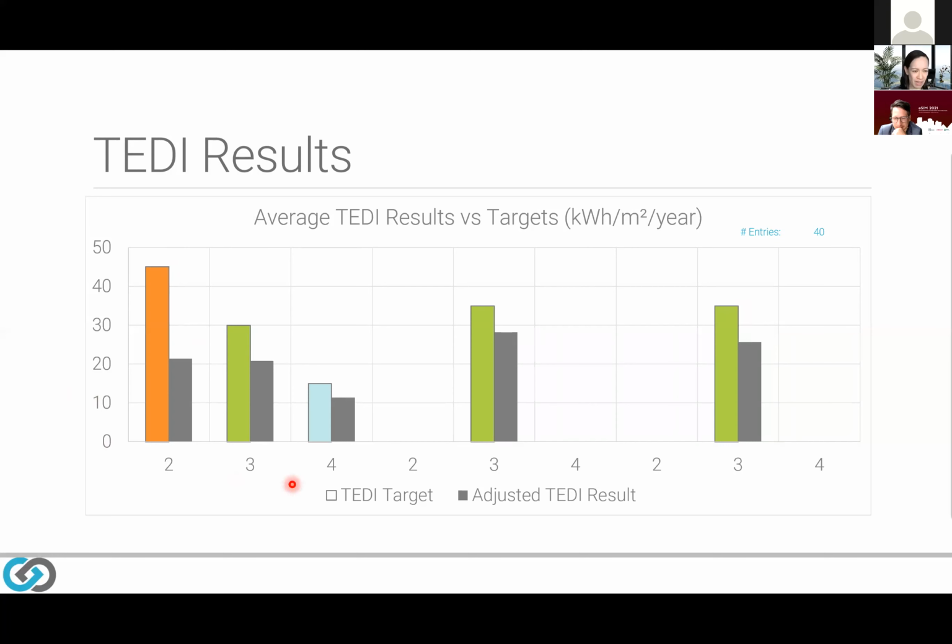Again, if we just look at climate zone 4, one of the notable things we can see is that our buffer gets smaller as we get into the higher steps. And that's something that we've had a lot of discussions about with clients: when you start to get into these projects with smaller and smaller energy budgets, then essentially we need to really tighten up our designs earlier in the design process.